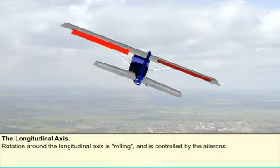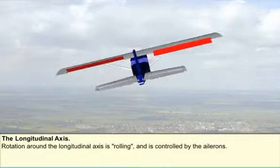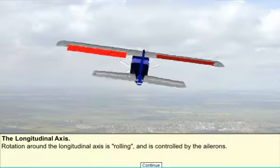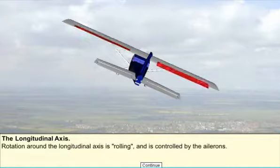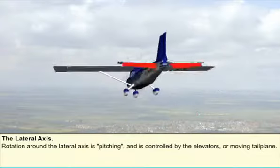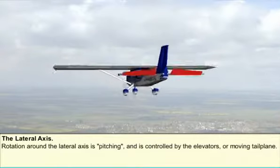Rotation around the longitudinal axis is rolling and is controlled by the ailerons. Rotation around the lateral axis is pitching and is controlled by the elevators or by a moving tailplane.